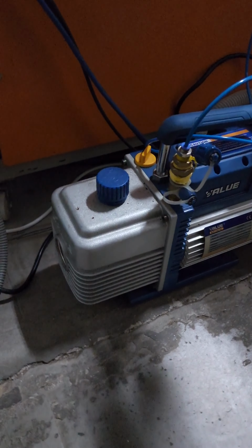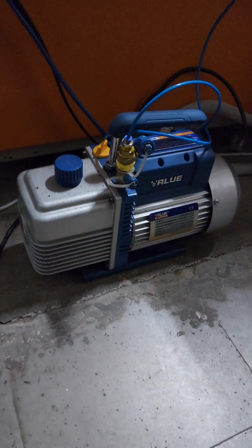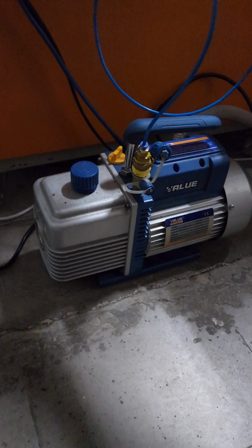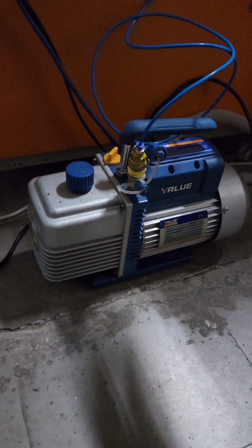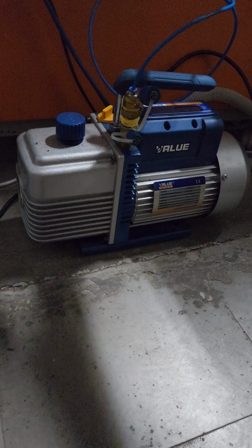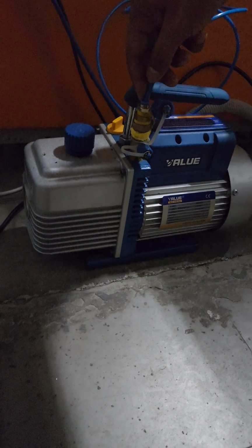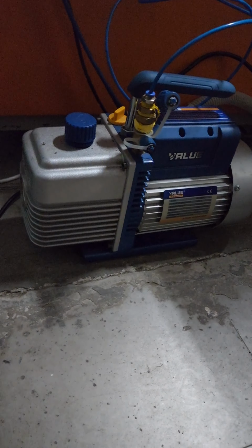In case we have to remove the gases and create a vacuum inside the constant volume combustion chamber, this exhaust line is connected to a vacuum pump. Once we turn on the vacuum pump and close the other valves, all the gases get flushed out, and we have created a vacuum that mimics the suction stroke.